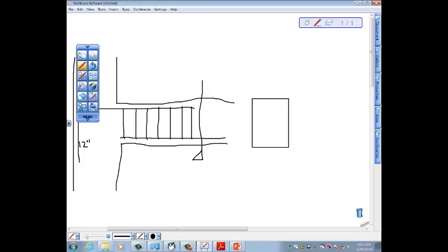So I'm cutting through this beam and I'm looking this way. Everybody understand that? I'm chopping through this. Now this is what I'm looking at. Now I want you to draw these pieces of steel in this part like you're chopping through it. So you're going to see little circles for your 2 number 9 bars at the top. And you're going to see little circles for your 2 number 8s at the bottom. And then you're going to see your stirrups going around it.